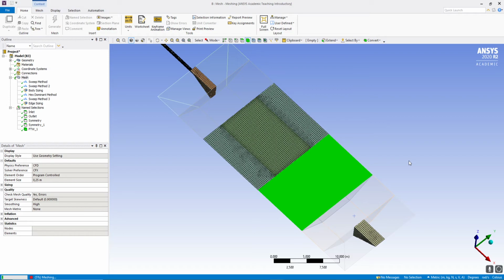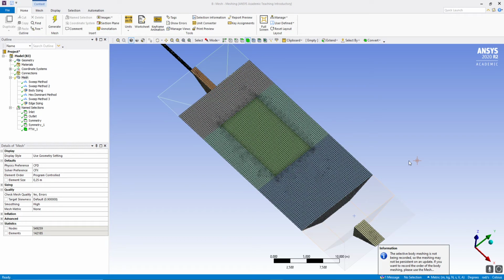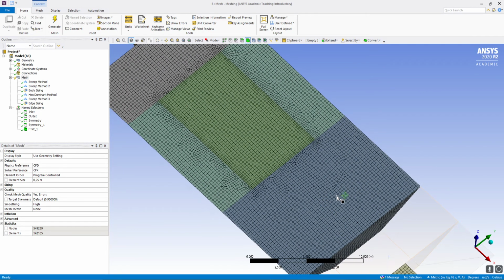so you can see that for any geometry that we generated relative to this problem, we would follow a similar order to this one. We would generate the inlet, outlet, and vegetation mesh, then we would generate the one that has the higher contact surface for the vegetation, then the higher contact surface with the inlet and outlet pipes, and then so on and so forth. And you can see that it's a very well organized mesh.